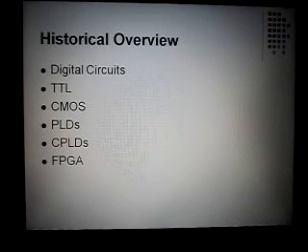And as we know, by using fundamental gate logics we can develop any logic from combinational to sequential. So by using these fundamental logic gate arrays, PLDs were created, after TTL and CMOS. Now what is a PLD? A PLD is basically a device which contains arrays of AND gates and OR gates. These arrays were developed to be programmable, so that we could create logic of our own choice rather than have vendor specific logic which cannot be modified later.